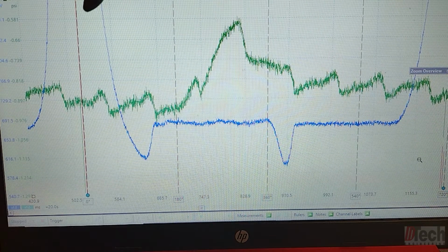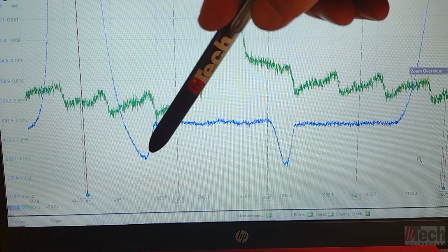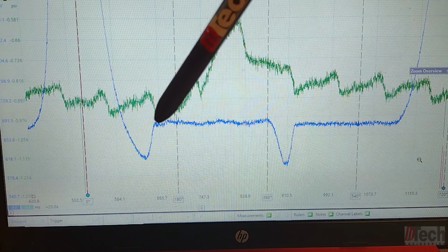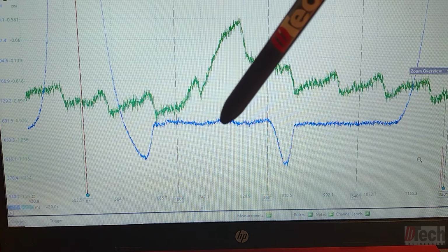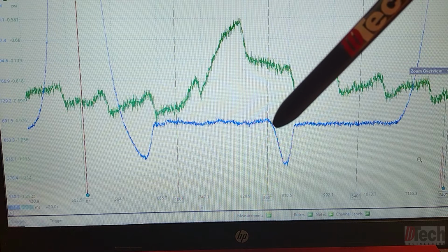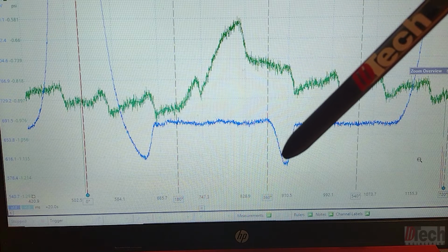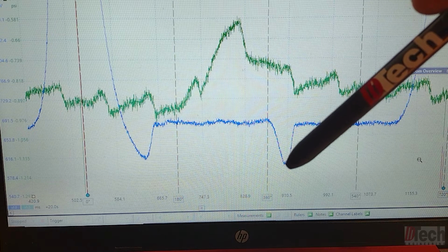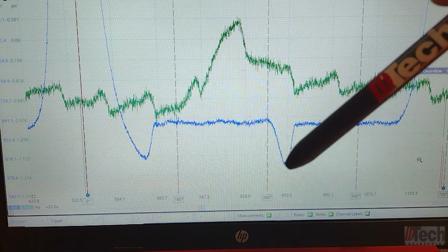So here is the expansion coming down, exhaust valve opens, it relieves, pressure changes up to atmospheric. Here's the exhaust stroke. This column now is intake stroke. Pressure is going down into vacuum until this point. That is when the intake valve opened, because the piston was traveling down.